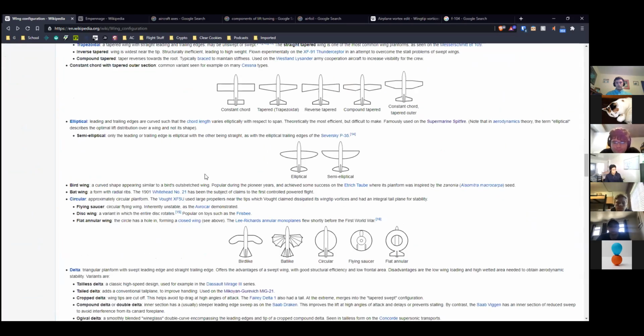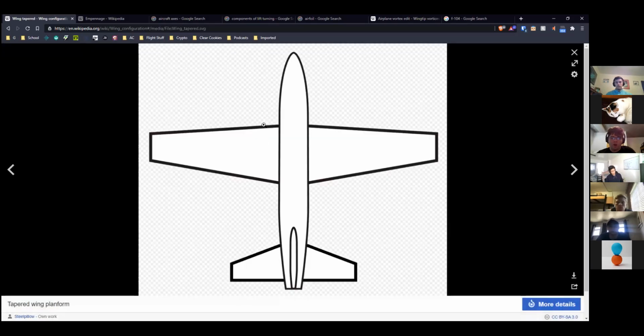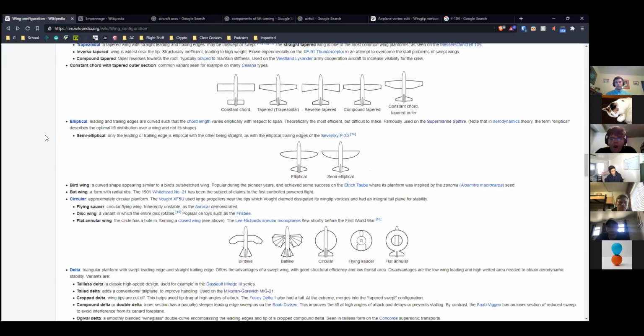And yeah, so if you choose this design, you would want to have a really good reason that you need a perfect lift distribution, because it's harder to manufacture than the other ones. Although this shape would be easy to cut out on paper, if you think about the airfoil, that means the airfoil is changing literally according to this function that you would then have to reparameterize into 2D and then somehow manufacture. So it's harder than even this, which is at least just a bunch of linearly varying airfoil sections.